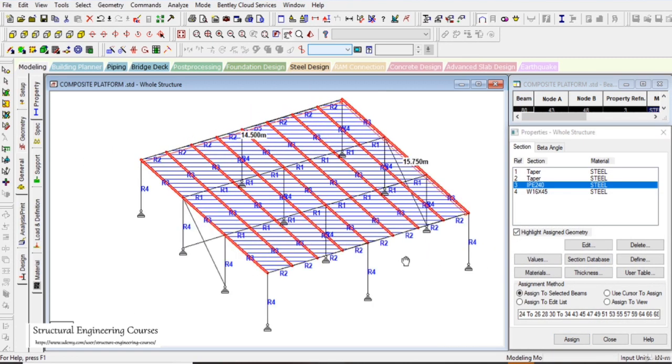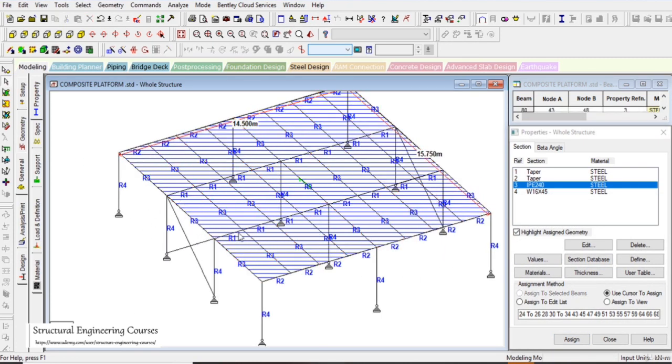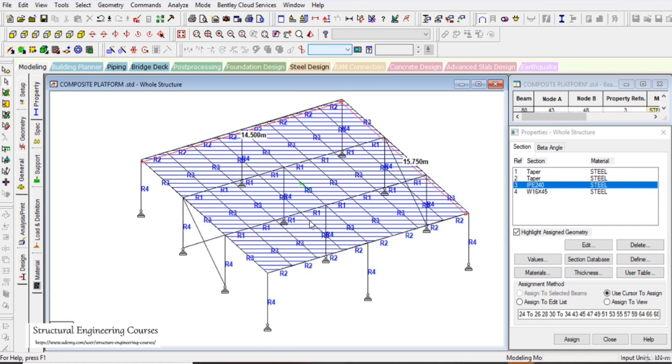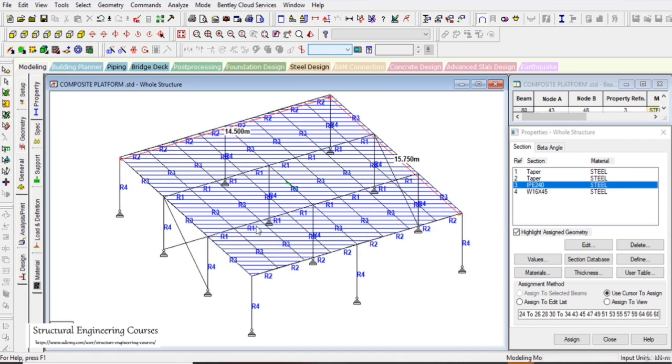And the reason why we have provided the bracings along this axis is that the shear connection axis is a much weaker axis as compared to the moment connection axis. So that is why we have provided bracing along this direction. And as a simple thumb rule, I always recommend you to provide bracing along the shear connection directions. Now we can see that we have assigned the properties of the columns and beams, but we have not assigned any properties to the bracings here.